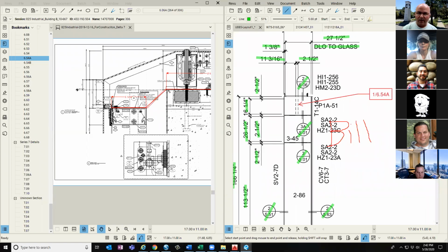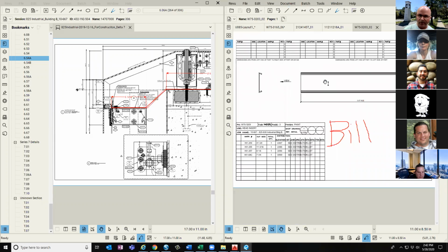Now, as I'm finishing up that head member, I see that I have a couple of head fillers here. So I'm going to look, I've got one that's a straight cut, and I've got one that's got a miter and a notch on it. Well, in this case, this looks a little weird to me because this is not the standard logic of what I'm expecting to see. This part will be hard to snap in if it's got a miter and a notch on the same piece. So I'm actually going to mathematically change this. I don't want to see this with the notch on this end. I'm going to cross this off. I only want the miter on here.